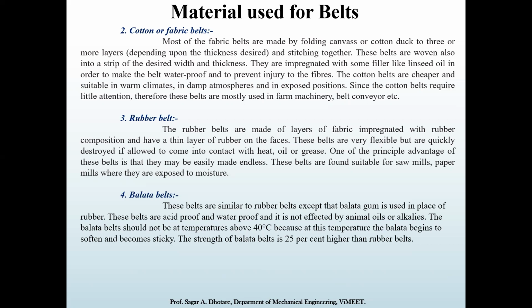The cotton belts are less costly, or cheaper, and are suitable in warm climates, in damp atmosphere, and in exposed positions, where they are directly exposed to the environment. In such conditions, these fabric or cotton belts are mostly used.